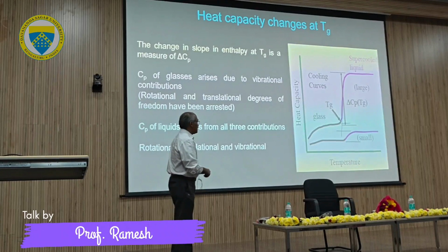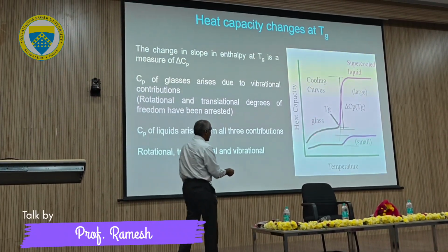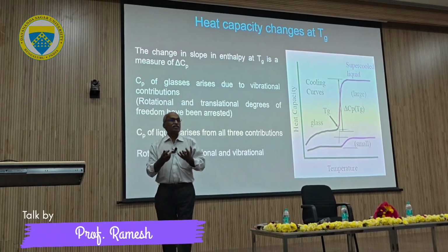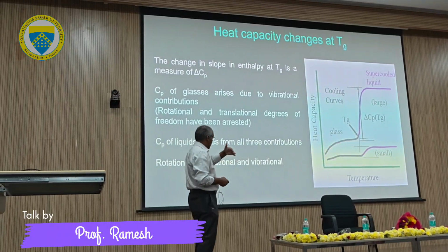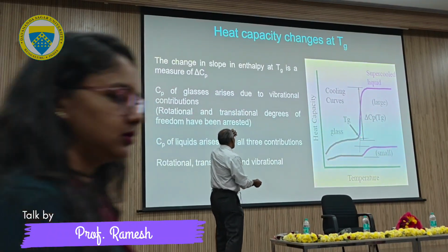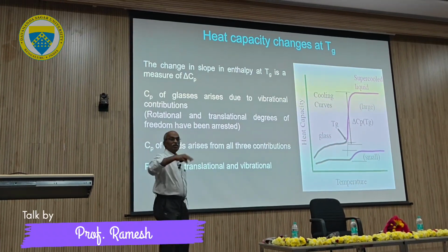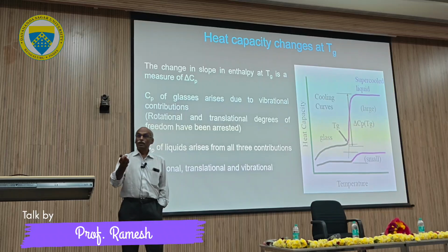It gained the rigidity from the other side. Now, at this point, it should lose the rigidity. That means it should soften at the glass transition temperature. It's not the melting temperature. It's 2/3 of the melting temperature. It's very low compared to the melting point, but it loses its structure. So in a solid, you have only the vibrational motion, right? So it leads to the specific heat. What is specific heat?